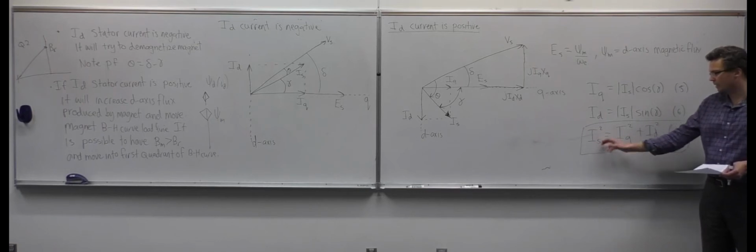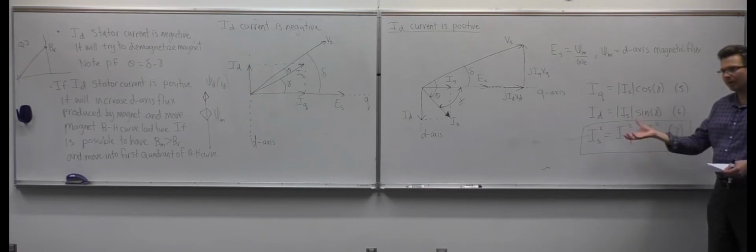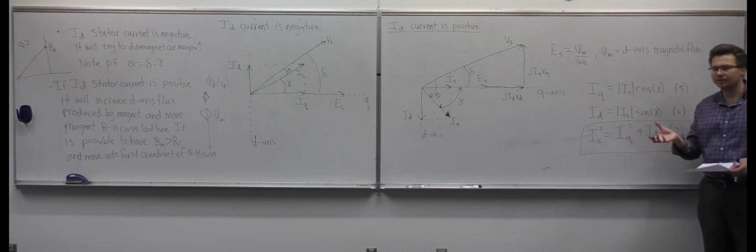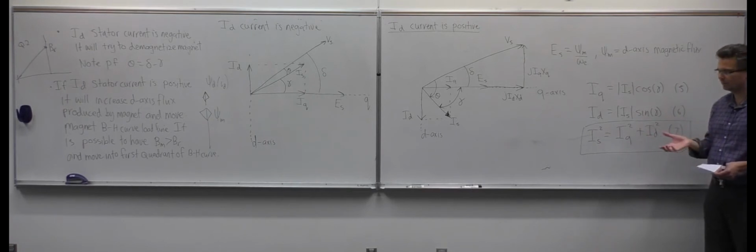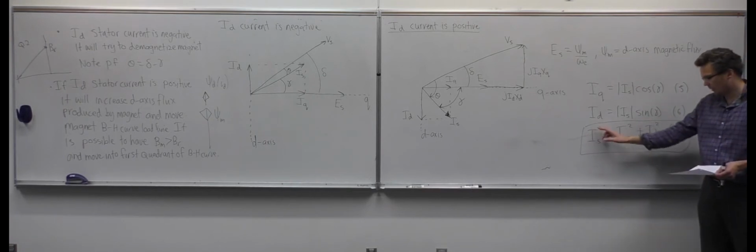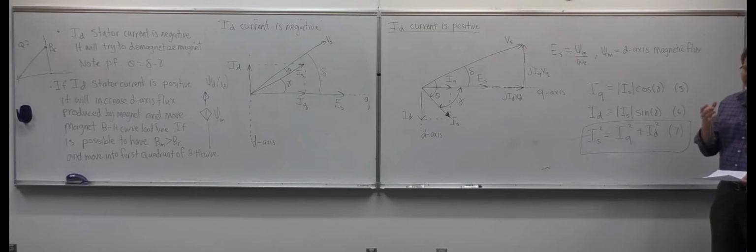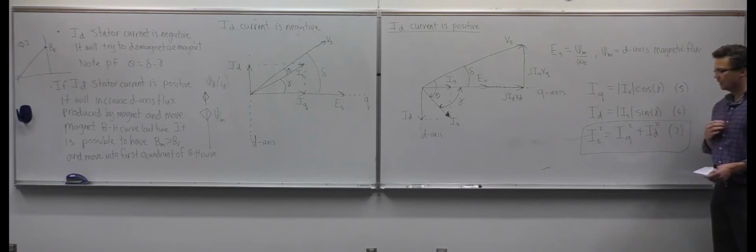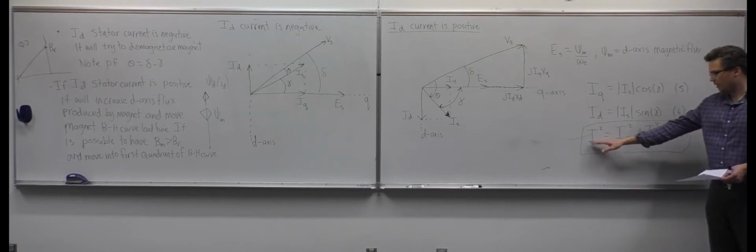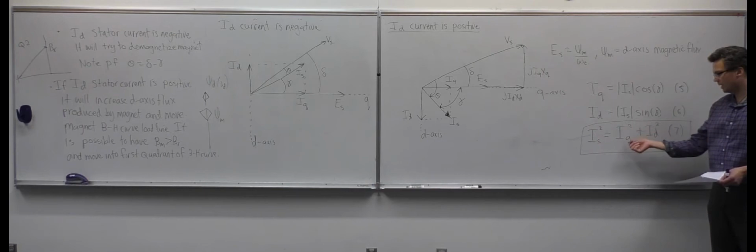The inverter that we are providing to the machine will have a particular rated current. We can't provide more than that to the machine, so that puts a complete upper bound on the machine operation. Of course, there's a rated current that the machine should be run at, and a peak current that the machine should be run at. So that's really the limit. You can think of this as the limited supply current, and it can be made up of an IQ component or an ID component.